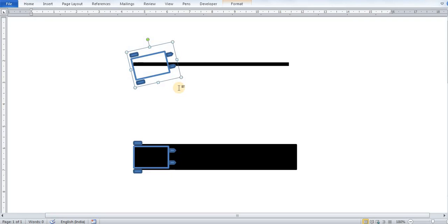If the right sensor is showing black color, we need to turn to the right. And the fourth condition is we come to the end of the road and we see a black end. So if both sensors show black, then we should stop. That is what we need to start coding. So let's go to coding the thin line variant of line follower.